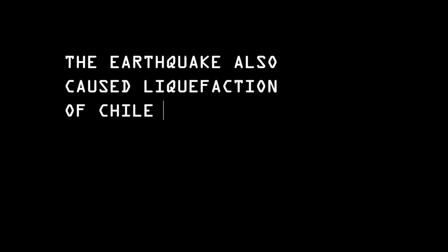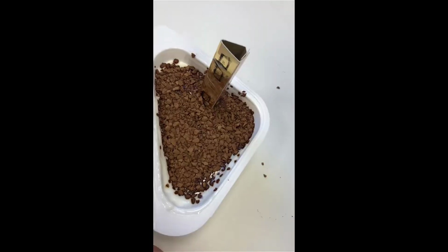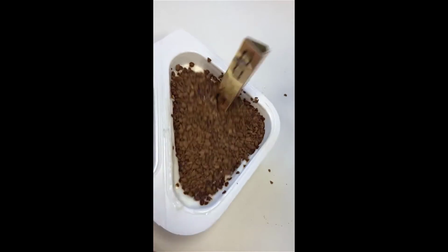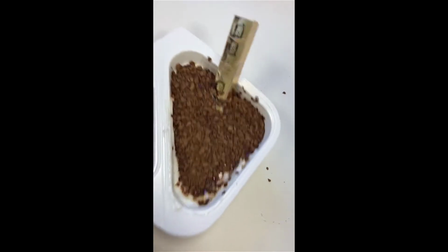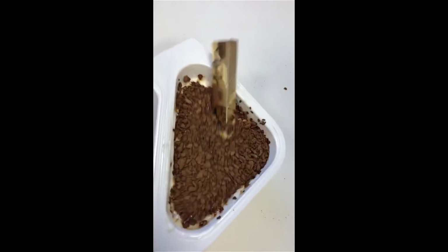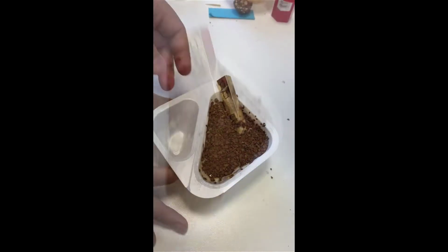Soil liquefaction is the phenomenon of saturated or partially saturated soil losing strength and stiffness due to applied stress, causing a solid-based material to behave like fluid. As seen in the video, the building started to sink into the ground after several lateral waves. This phenomenon induced damages to road infrastructure like Highway Route 5, railroad systems, buildings and houses.